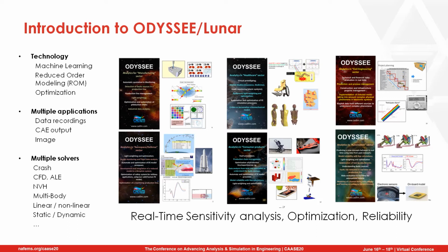solver, any partial differential equation, be it crash, CFD, NVH, etc. It can handle linear, nonlinear, static, dynamic, bifurcation, buckling, etc. So it's completely independent of the solver because it only looks into the output of that solver. It is used for various real-time sensitivity analysis, optimization, reliability. By real-time, we mean interactive, not to be confused with system engineering.